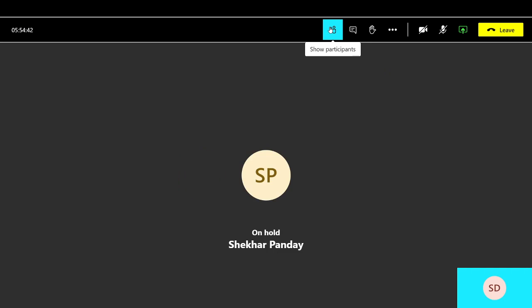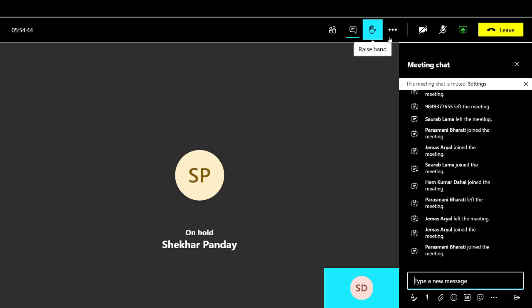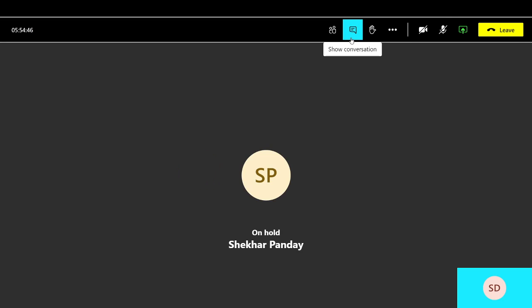We need some reference pressures though. So for a given power torque meter, oil pressure differs with engines. So therefore, necessary obviously to establish a reference figure for each engine on a test bed after new build and overhaul. So when you get an engine, rebuild an engine, you put in what's called a test bed.